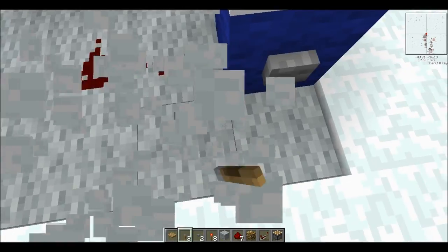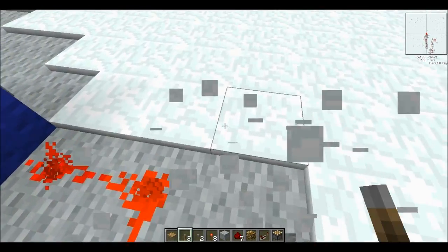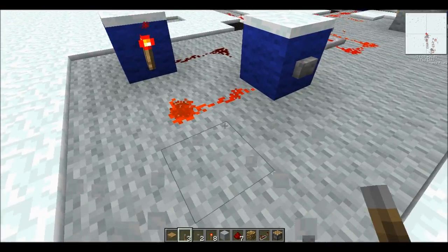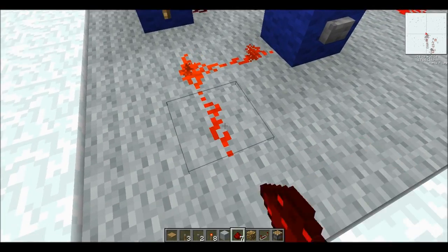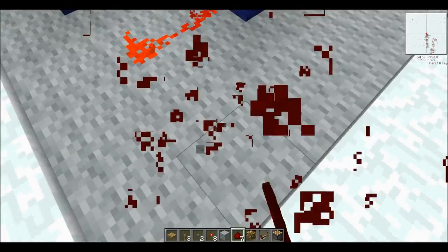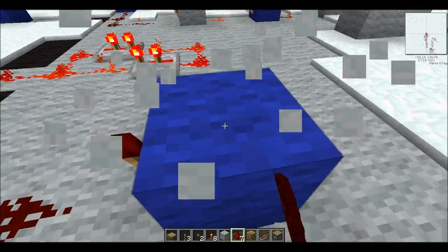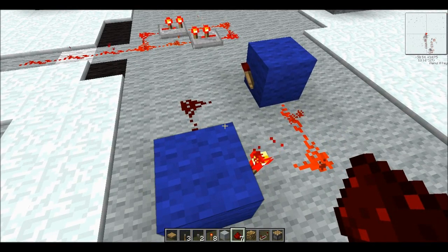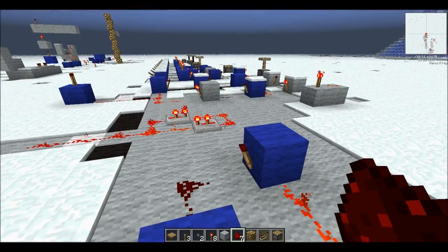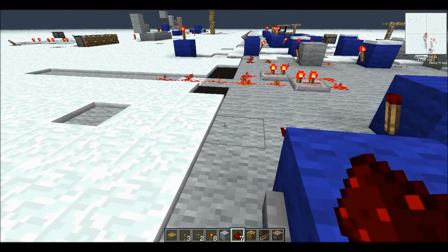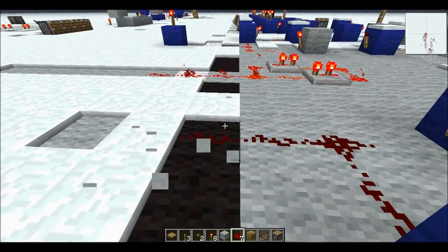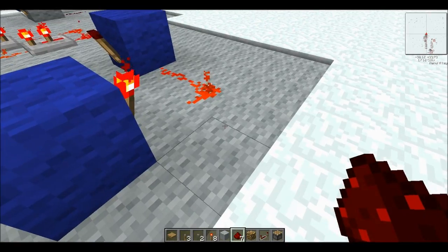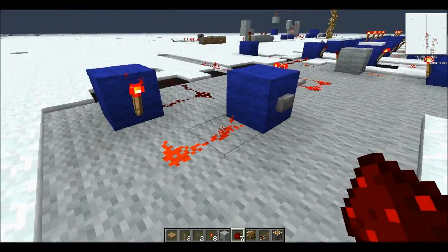The last thing I'm going to talk about in this lab is, in a sense, a logic gate. It's called an RS NOR latch. RS NOR latches have several different uses, but their main one is based around the fact that they're what is called a binary memory latch, or a single cell memory cell. The reason they're called that is they remember what the input is. Remember in quote marks. It's a machine. It doesn't actually have memory, well, memory in the sense that computers have memory.